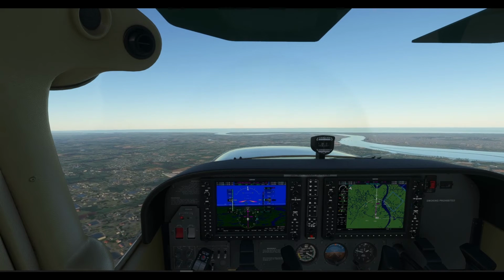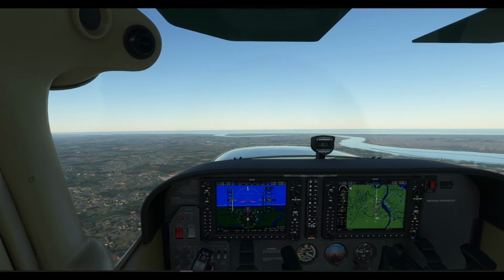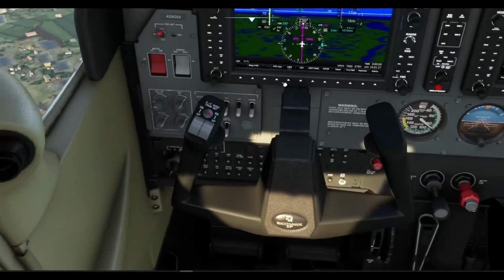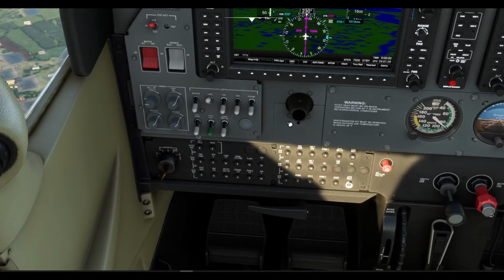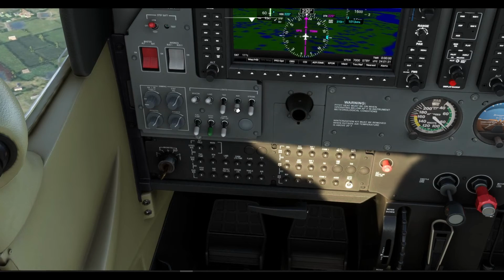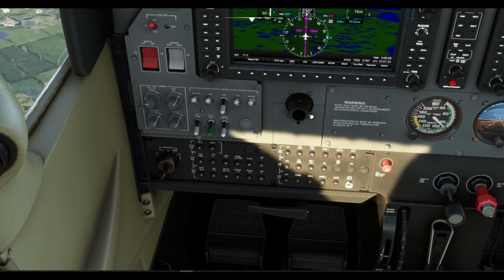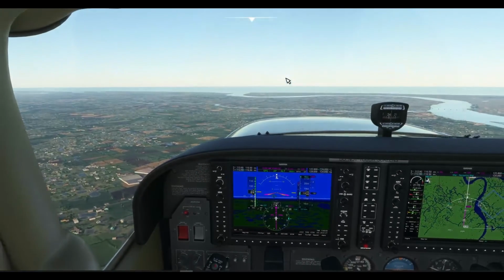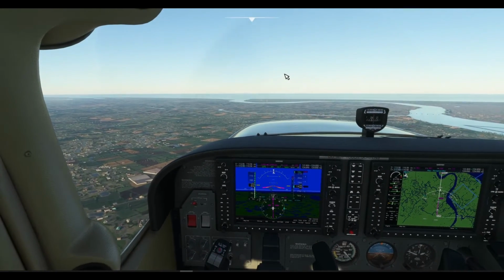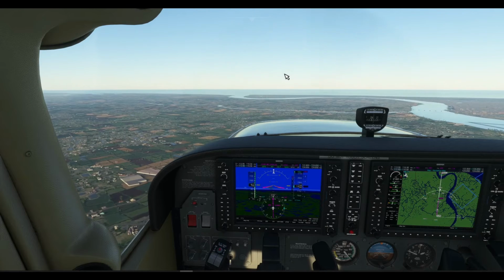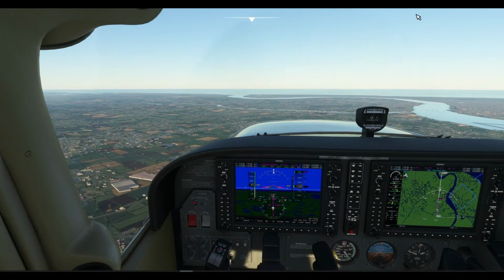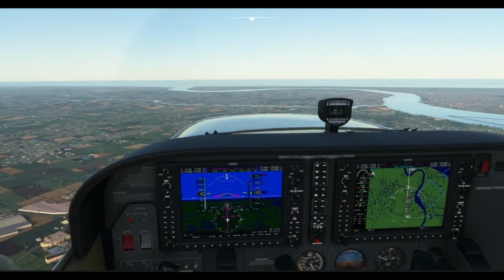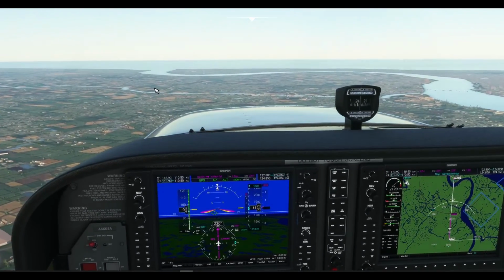When the descent starts, I will put one notch of flaps. Let me turn on the landing lights. Oh, beacon light and lamp light is not on. Also, strobe light is also not on. So as I have said previously, I am not getting into the geek situation today. Just doing all the basics, and I'm going to do a Unicom call. Chattogram traffic, Mike India Sierra on finals for runway 2-3.